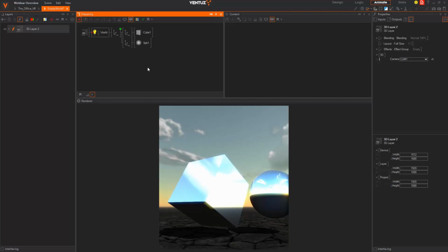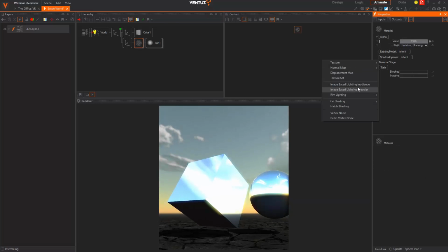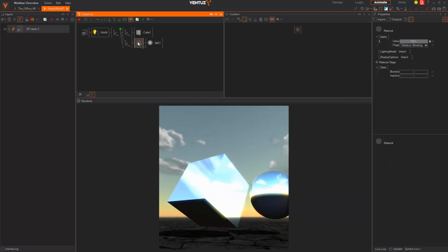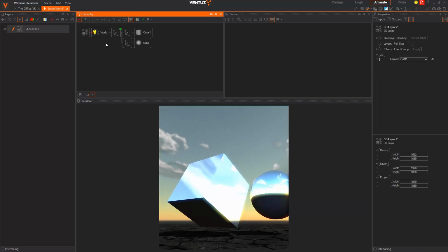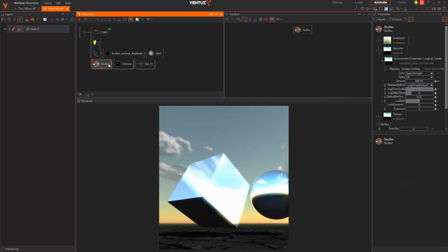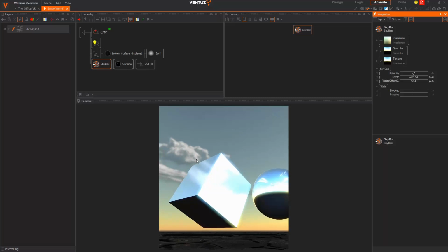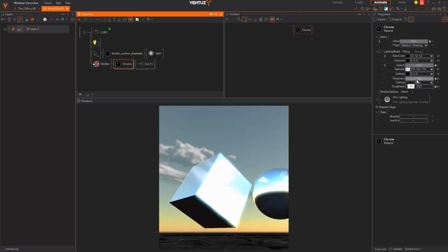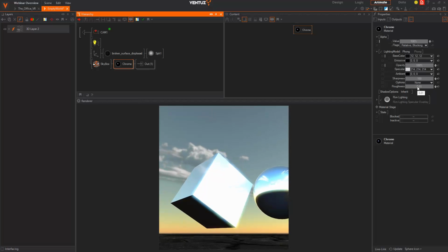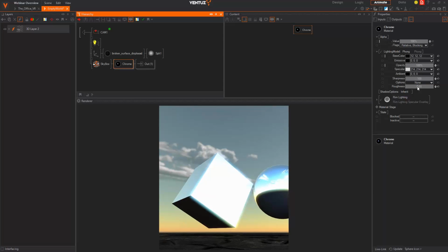Also very interesting then is our material system, which enables you, for example, to use image-based lighting. You can not only do this material or object-wise, but you can also create a skybox, which also enables you to create an irradiance skybox and a specular skybox, which will then be used on all the materials, for example with the roughness, so you can also change the roughness of your materials, so that you can really use this physically based rendering workflow that is now trending along the 3D real-time engines.